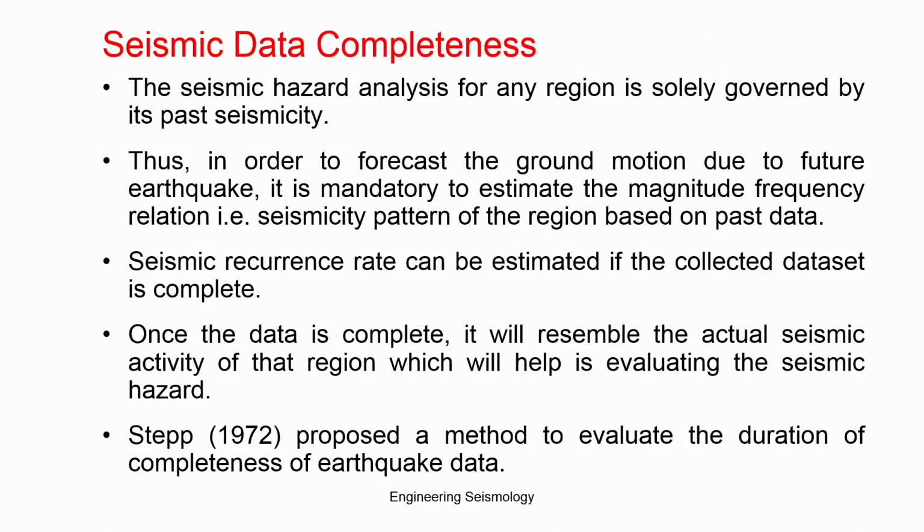After declustering, the first part is you have to understand whether your data is complete or incomplete. What is meant by complete? Complete means that for your region you should have the full range of magnitudes recorded in that particular place. For example, for the last 10 years, after installing the seismometer, I have everything from minor to major earthquakes recorded. That is the complete period.